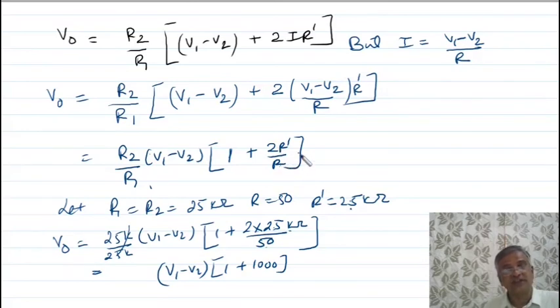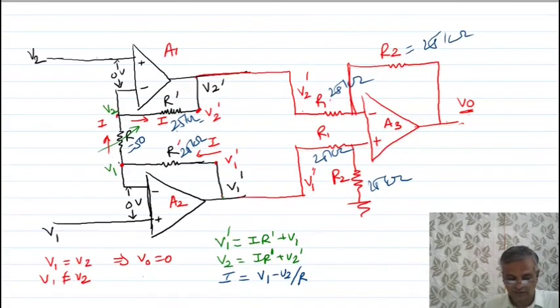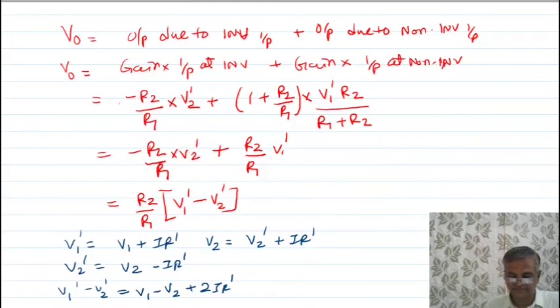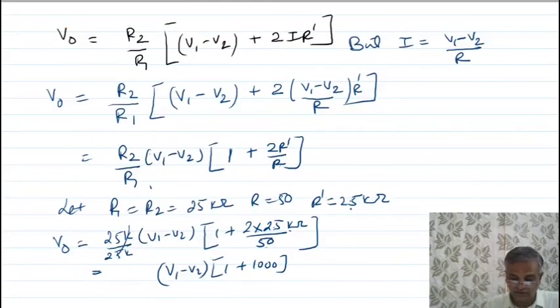So to avoid such a thing, I think you understand. You are changing the gain of the amplifier by changing the R, by this potentiometer. But by mistake you are making this R 0. Then your gain becomes infinite.